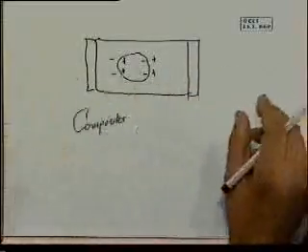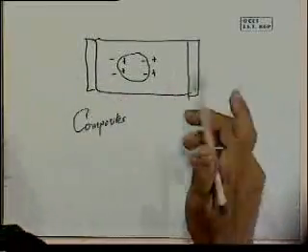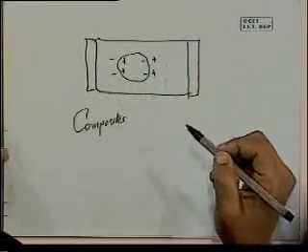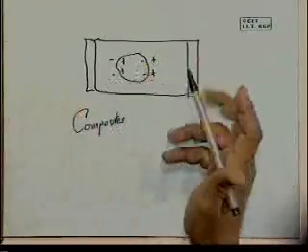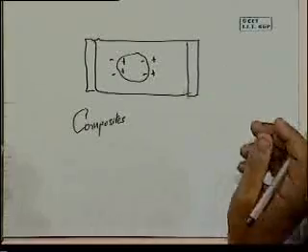Now, unfortunately, interfacial polarization is structure dependent and processing dependent. It depends on the particular nature of these boundaries that have formed or how they have been dispersed and so on. So it's not as easy to treat it and give it some average value like we did for P average for the electronic or ionic cases and so on. So we simply cannot club it in with the rest of it and treat it in the same way. There is no simple equation that will allow us to say, okay, the average value of the dipole moments that are created. It will depend on where the grain boundary is and how many grain boundaries there are and so on. So that's the difference.